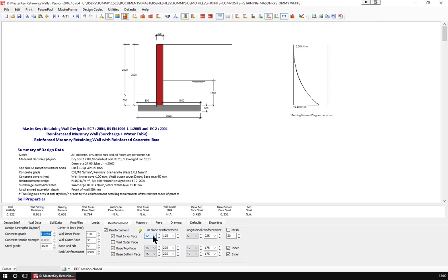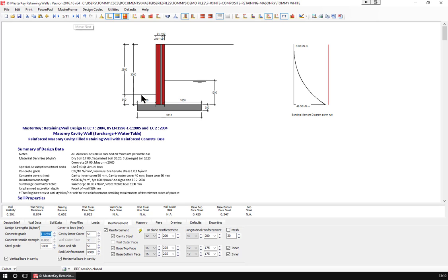you will see that I have in plane 12s at 125, so we're putting pairs of 12s every 250, 225, so you'd have to be working with hollow core blocks and mortaring them up to actually get that to work as little pockets. I do not like these reinforced single skin walls. They're not very nice to work with at all. Naturally, your other option is to go for a cavity reinforced wall.